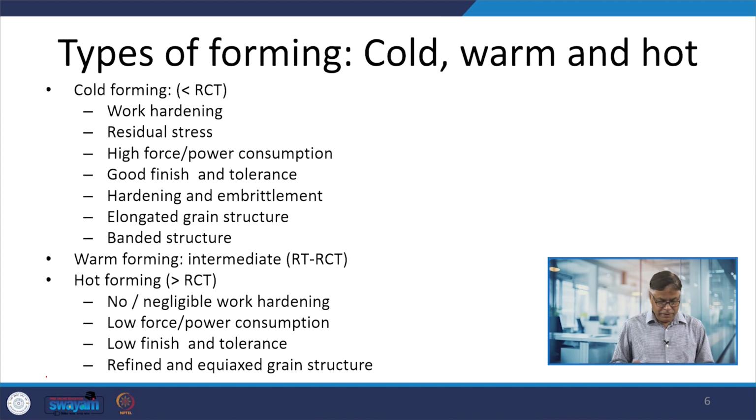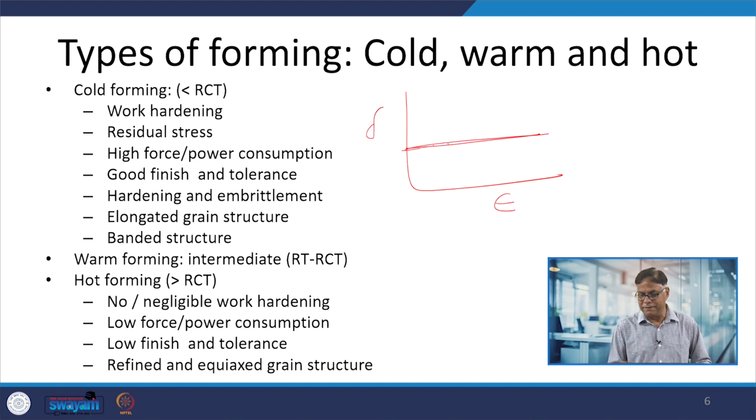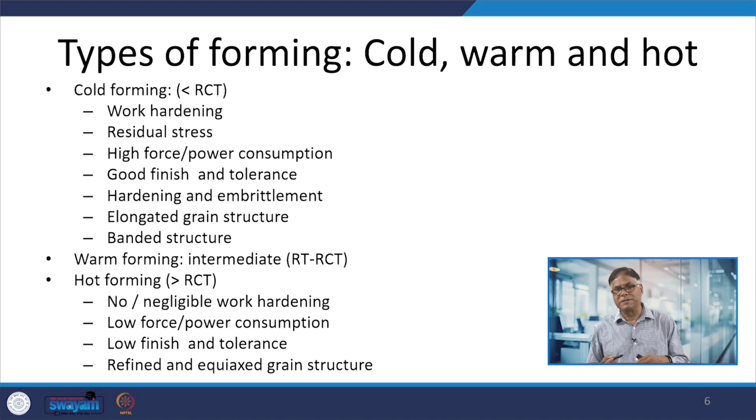Okay. Now, hot forming is a plastic deformation carried out above the recrystallization temperature, so that the metal gets softened, the yield strength is reduced, and the material becomes more ductile. These things reduce the work hardening tendency. The material may be strained, but at a high temperature the strain hardening is almost absent in the hot working condition, while otherwise, with continued plastic deformation, the metal gains more strength, so it requires higher levels of stress to cause further plastic deformation.